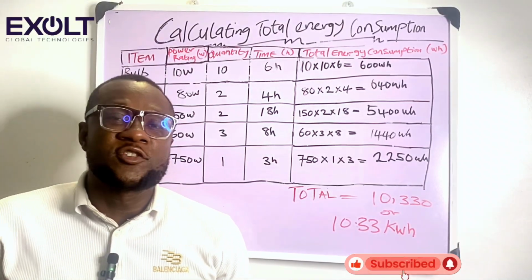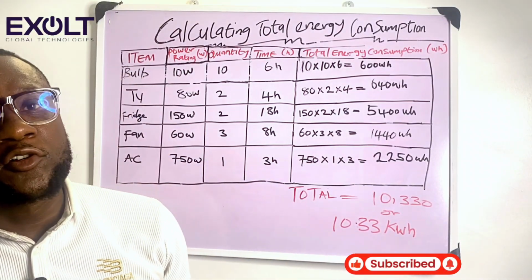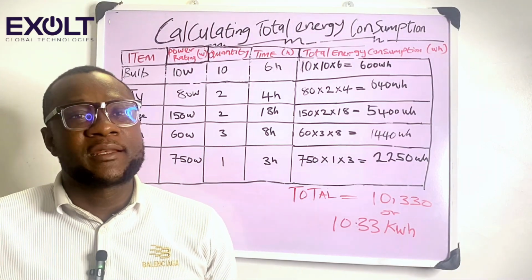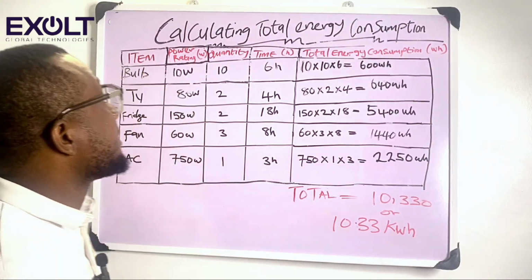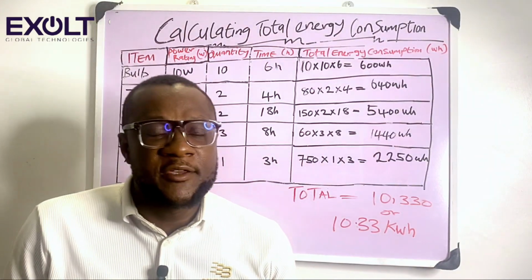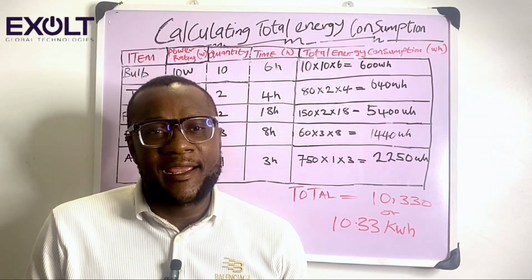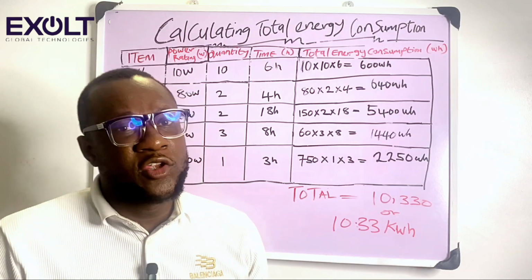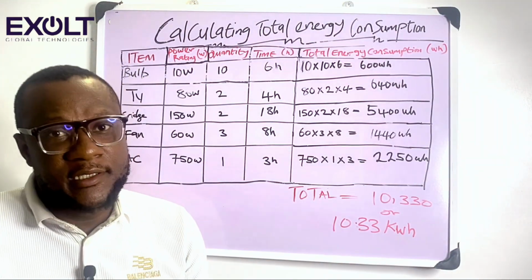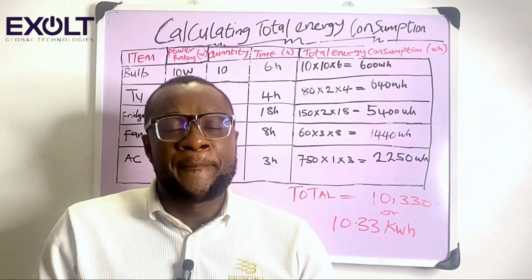Okay, there are a few things you need to put in consideration before giving a proper solar design. One of them is calculating the total energy consumption. If you must give an adequate solar design, you must first conduct what we call the energy audit, the energy analysis.